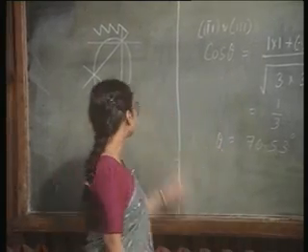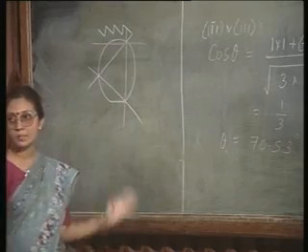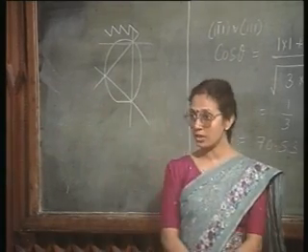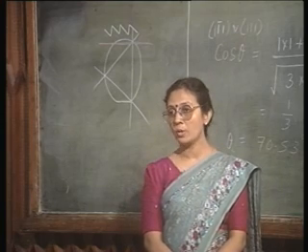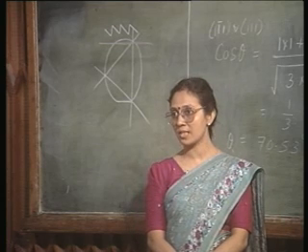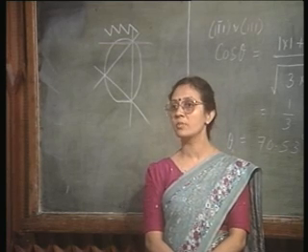So, you will find that along this direction it is breaking cleanly, because it is cleaving along a natural direction of 110. But when you try to cleave in a direction perpendicular to your first scribe line, it is not going to cleave cleanly.